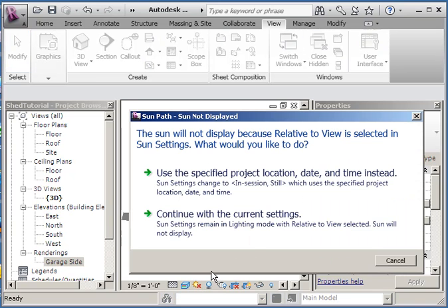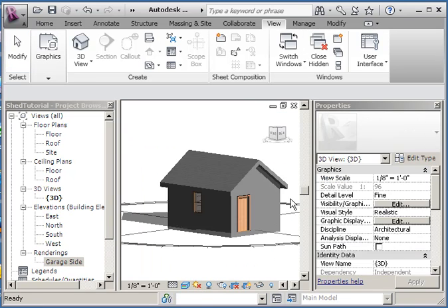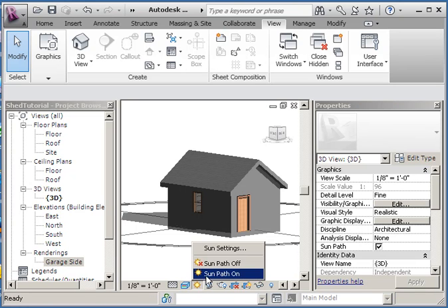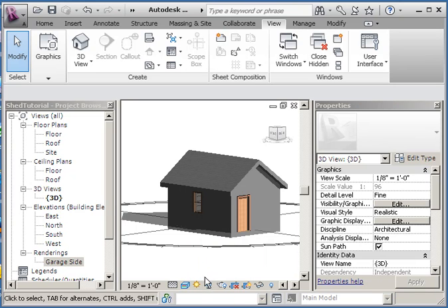When you turn the sun path on, it gives you a circular azimuth or compass reading, and that helps some people to understand how the sun is tracking in their house so they can plan for passive solar energy and that kind of stuff. Doesn't look good on a rendering, so we turn that off. The other buttons here are for fine-tuning.